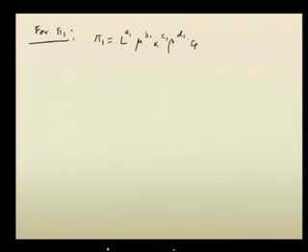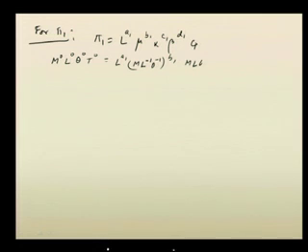This is pi 1, and as we have done in the previous cases, pi 1 is a dimensionless group. So, we will write M to the power 0, L to the power 0, theta to the power 0 and T to the power 0 in terms of the dimensions. So, L to the power A1, then we will write M L to the power minus 1, theta to the power minus 1 whole to the power B1, then k is M L theta to the power minus 3, T to the power minus 1 whole to the power C1, and then you have T to the power minus 1 whole to the power D1, and finally Cp is L squared theta to the power minus 2, then T to the power minus 1.